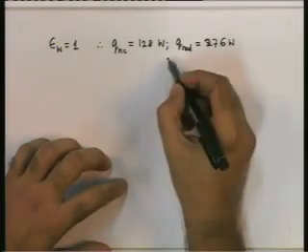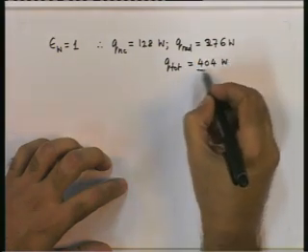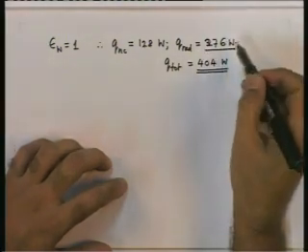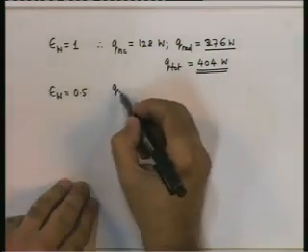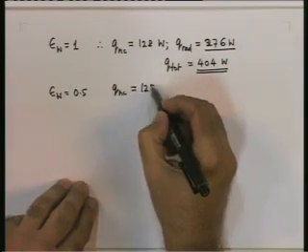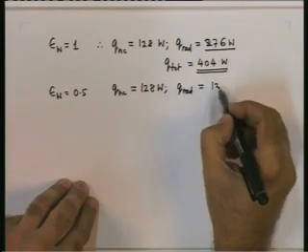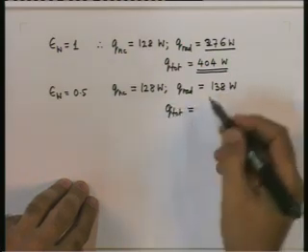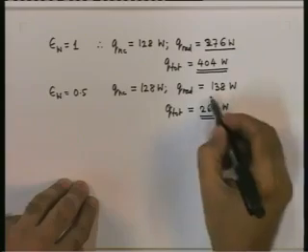The total turned out to be 404 watts. Notice that in this case the radiative contribution was roughly 2/3. Even with the wall epsilon equal to 0.5, the natural convection heat transfer would remain at 128 watt. The radiative component would reduce to 138 watt, and the total heat transfer would then be 266 watt. Even then you will notice that the radiation plays at least a 50% role.